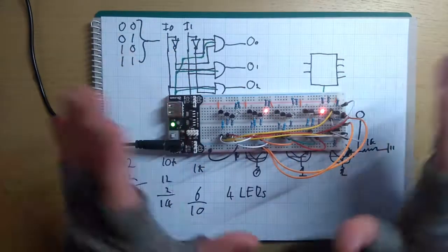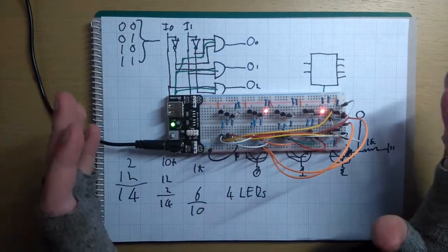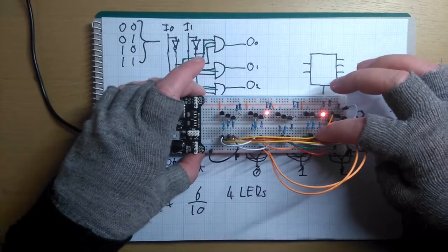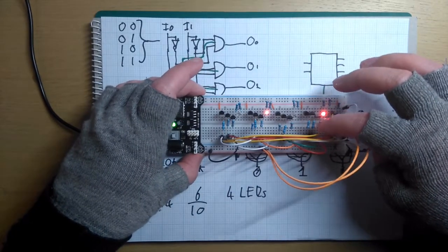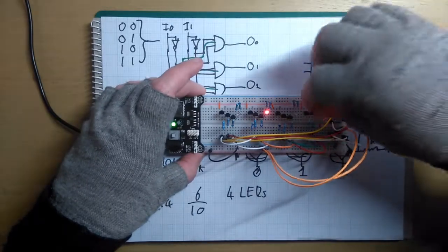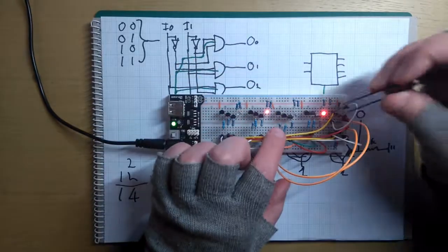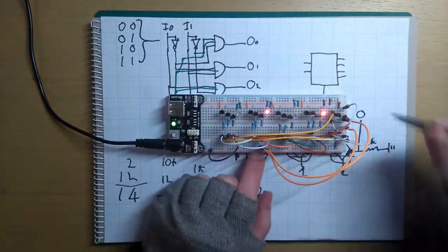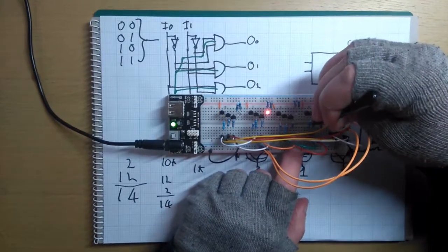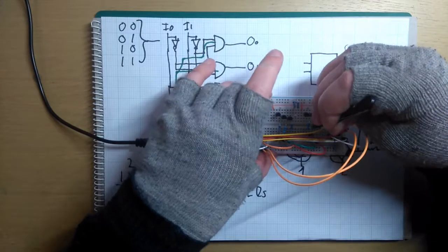Okay, sorry I had to cut that. I had to really sort of knuckle down and work out what that was. And I found out what it was. One of these resistors isn't actually a 10k, it's a 220 ohms. And that's what's causing the issue. Because it's got such low resistance, power is coming from here straight to that, like through other wires. So it's this one. So I'll turn it off before I take it out.